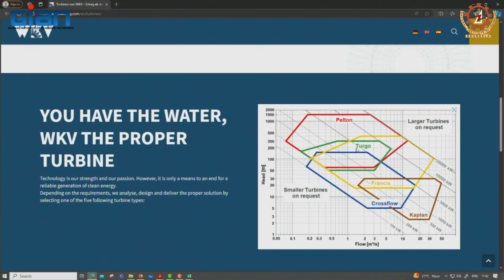So, this is a dependable one because this is given by a manufacturer through his own experiment, but some other graphs you get on the internet may not be that accurate. That is why I came here rather than using the one that we looked at, because their source we do not know, but a good reliable manufacturer will give a good turbine selection chart.